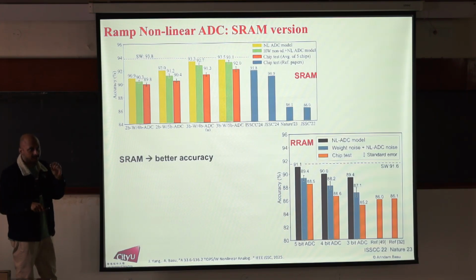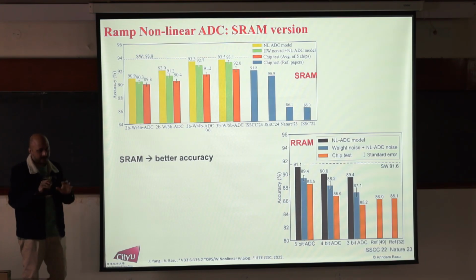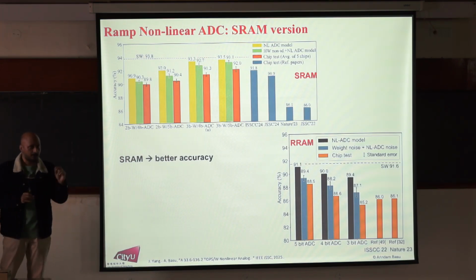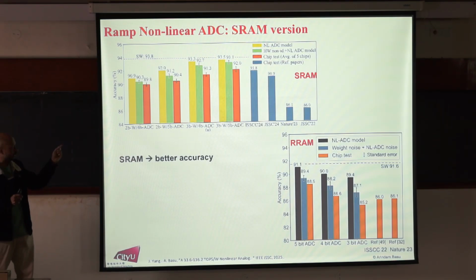With SRAMs, you would normally think you have quantization error for the ADC bit step. It turns out that for the RRAMs, the amount of write noise typically overpowers all quantization error and mismatch error in these SRAM-based in-memory cells. So accuracy-wise, SRAM wins 1-0.